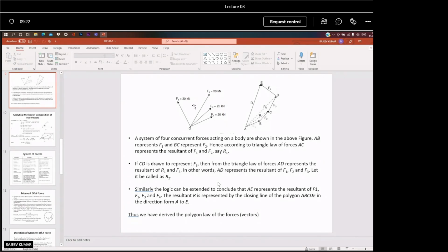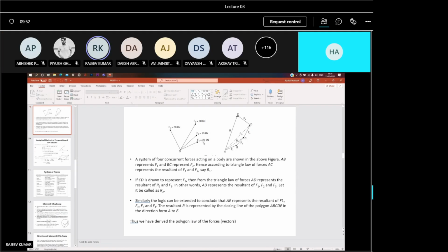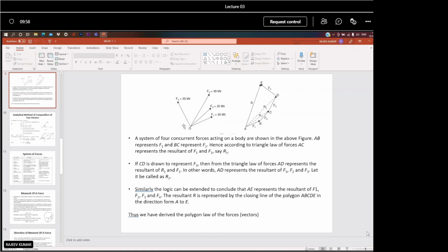Take this as your origin and this is the coplanar force. So we draw the xy line. Draw the vertical component from here parallel to the y-axis. This component will give you the y component, meaning the vertical component of the force, and this will give you the horizontal component of the force. In the same way you draw here. You are seeing that if you draw three forces in the positive x direction and one force in the negative x direction, you sum it all.